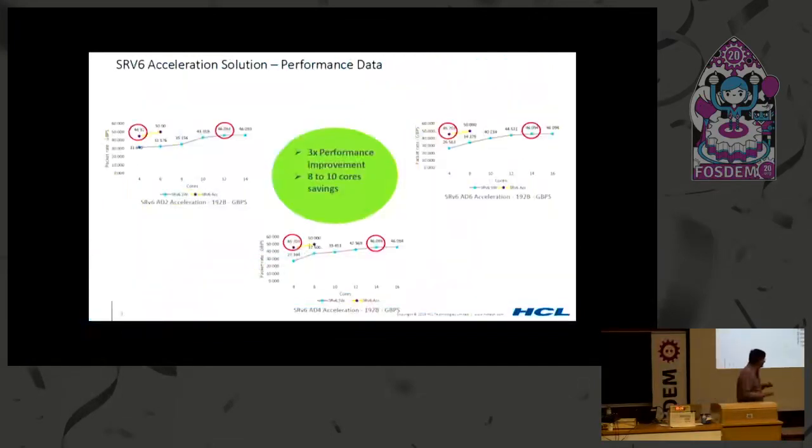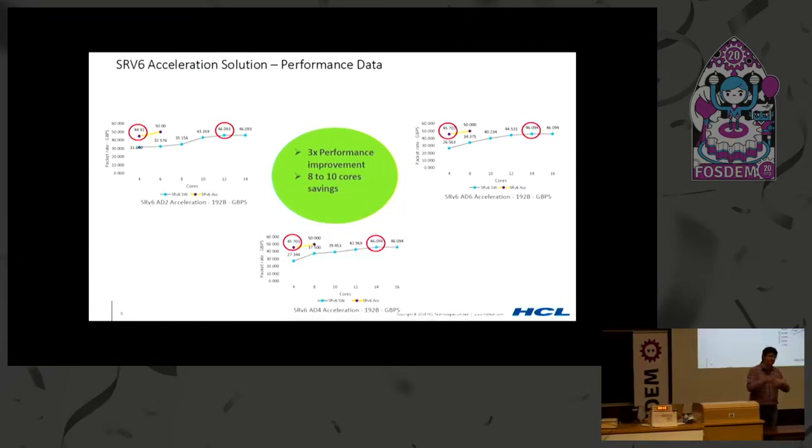Okay, let me summarize briefly what we can achieve using the FPGA. We are using the FPGA for the data plane to get better performance. What does better performance mean? In the software solution for the data plane, we use cores for packet processing. In some cases the software solution can use 14 cores, for example, which is half of the cores used by the server. With our accelerator, we can do this using 4 cores. It is 3 or 4 times fewer cores, leaving more cores for your processing. It is just an example of what you can achieve.